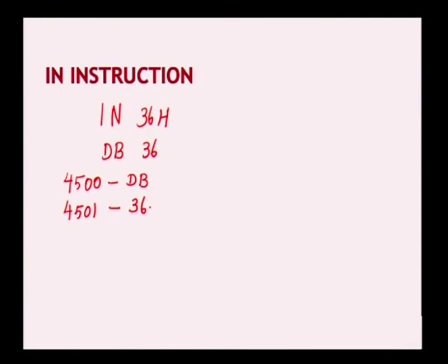So, during the program execution, this first one is represented as the opcode fetch cycle. We fetch the instruction which is already stored in the memory. The next byte is 36, which is the operand. Here we are performing the memory read operation, so it reads the data from the memory. These two bytes make up a 2-byte instruction, but actually one more cycle is required based on its operation.